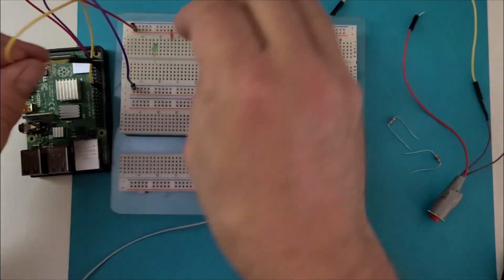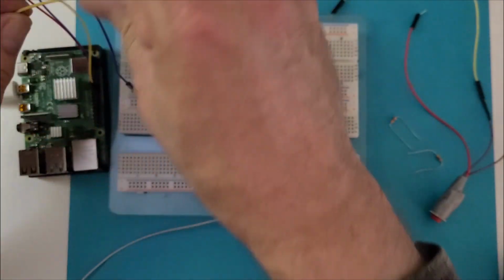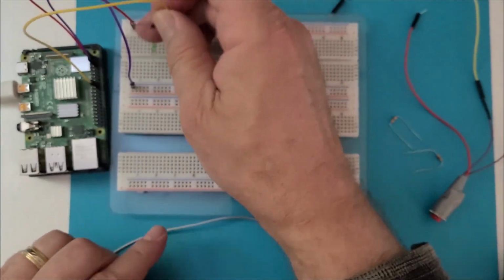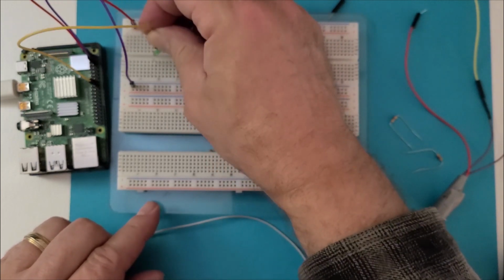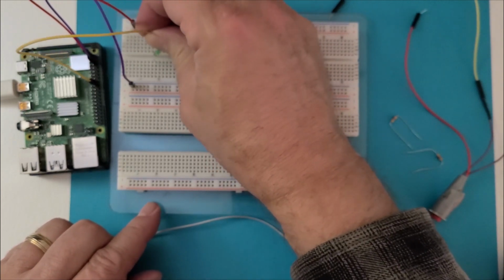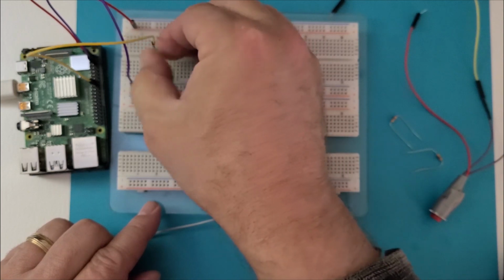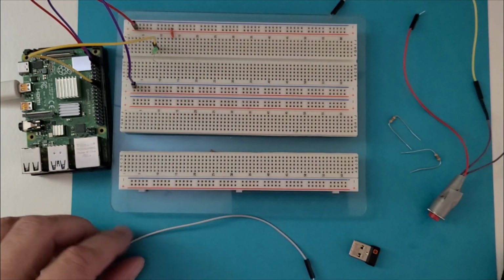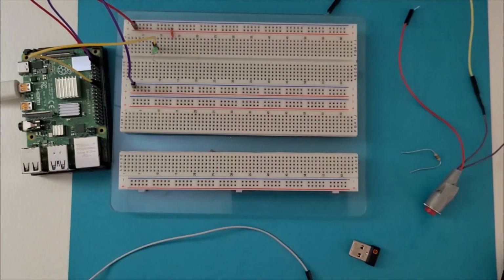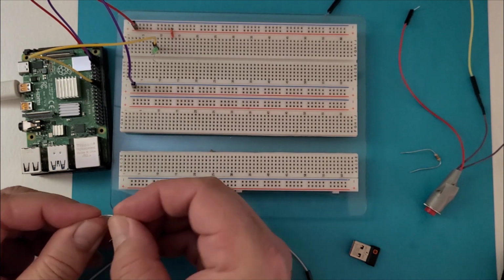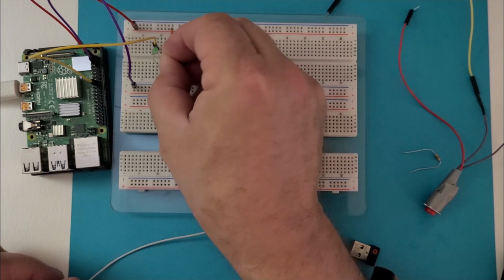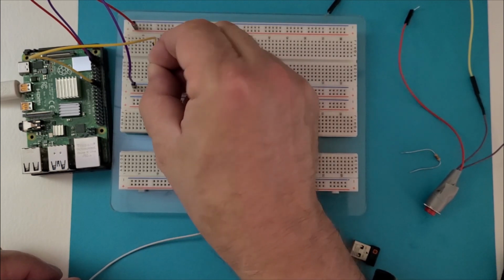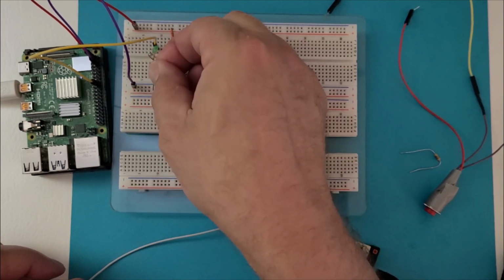And we're going to put this to the anode side of our LED. Make sure I'm on the right row here with it. So we'll stick it right there, hooked to the anode of our LED. Then we need a resistor, and it is the resistor that goes to ground on here. So just hook up to here, any one of these, and to the ground side.